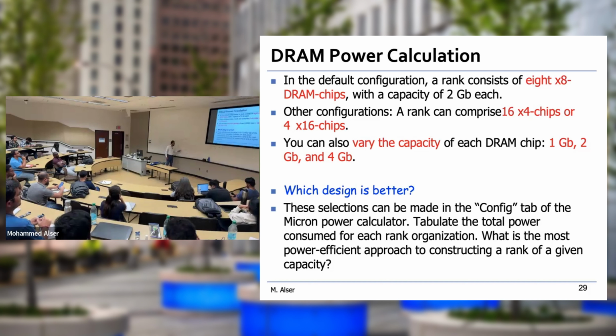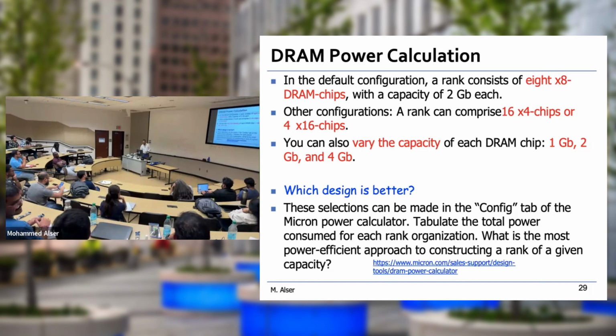So to answer this question is really not easy. You need to know the internals of this chip and how the clocking is connected to those and so on. For that, you can access this Excel sheet. There's a link in the book, but the link is not working anymore. It will point you to Micron, which is one of the companies producing this DRAM. So I updated the link for you. You can open it and you will see several Excel files. You can choose based on the technology: DDR1, DDR2, 3, 4. There's no 5, unfortunately, but you can at least choose 4.